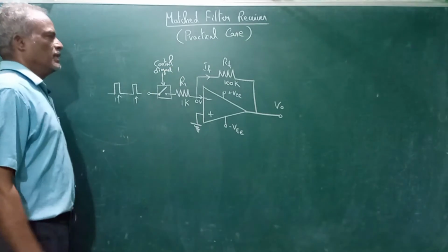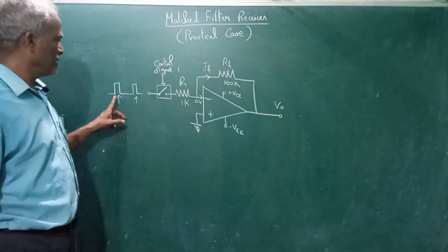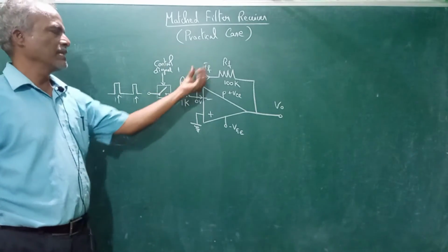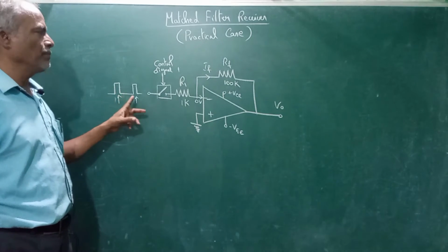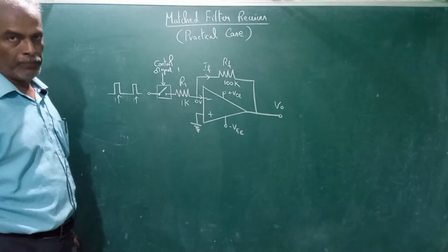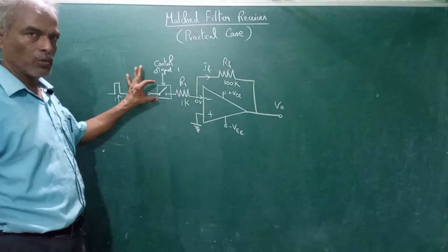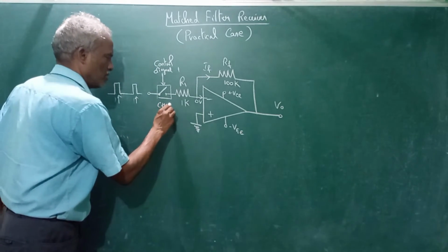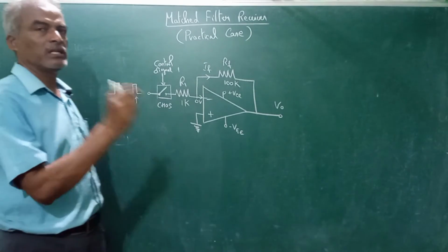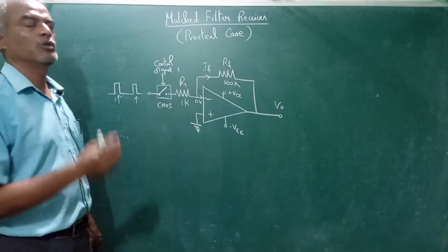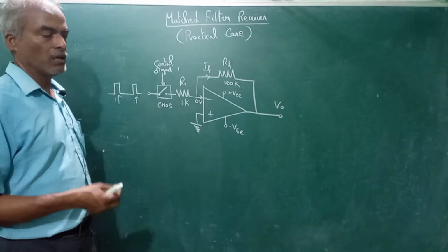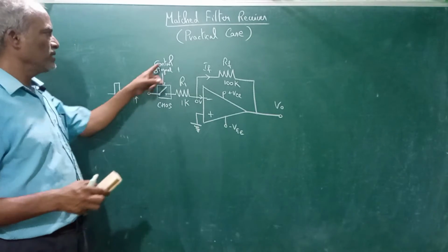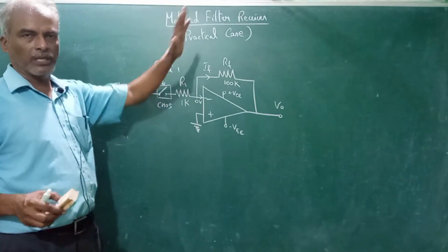The idea is, at the sampling point you have to close this switch, so you will get that gain. Other than the sampling point, the switch has to be opened. So some intelligence is required for controlling this CMOS switch. Basically this is made of a CMOS switch, and you see that the CMOS on resistance is very minimal. That's how you have to choose; there are a variety of CMOS switches, and you have to choose the proper switch. And this control signal comes from the microcontroller.